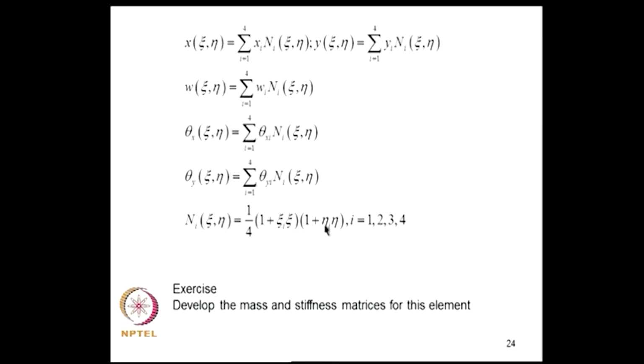Ni(xi, eta) is this, and x and y are represented using the same interpolation functions, and the displacement fields theta x, theta y are represented in this form. So, the exercise is to develop the mass and stiffness matrices for this element.